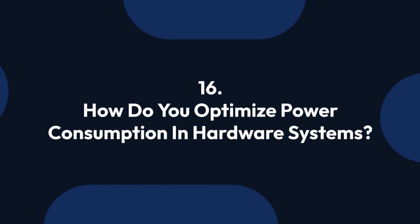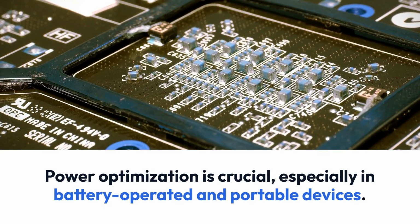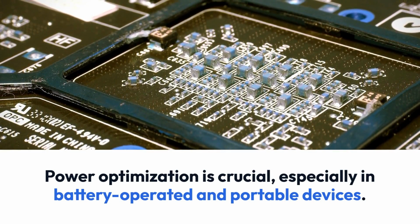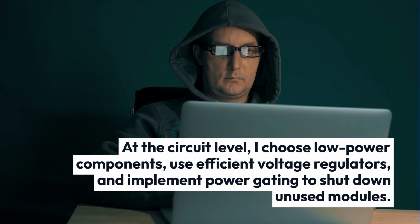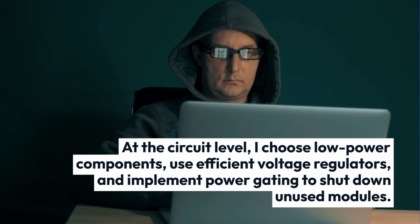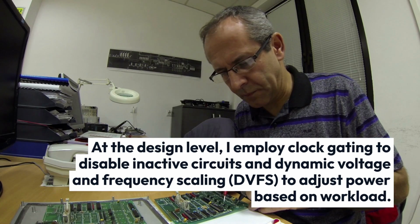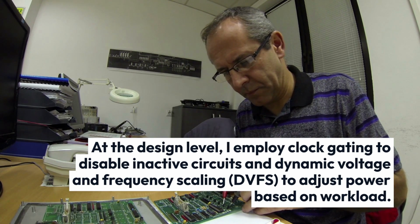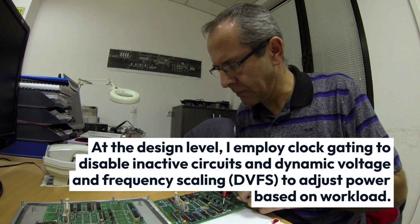16. How do you optimize power consumption in hardware systems? Power optimization is crucial, especially in battery-operated and portable devices. I apply multiple techniques to reduce power consumption. At the circuit level, I choose low-power components, use efficient voltage regulators, and implement power gating to shut down unused modules. At the design level, I employ clock gating to disable inactive circuits and dynamic voltage and frequency scaling, DVFS, to adjust power based on workload.